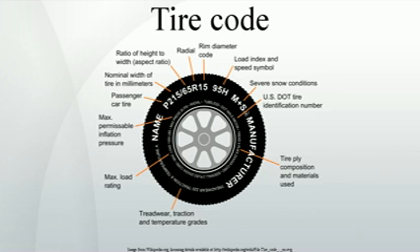When referring to the purely geometrical data, a shortened form of the full notation is used. To take a common example, 195/55 R16 would mean that the nominal width of the tire is approximately 195 mm at the widest point, the height of the side wall of the tire is 55% of the width, 107 mm in this example, and that the tire fits 16-inch diameter, 410 mm, wheels.